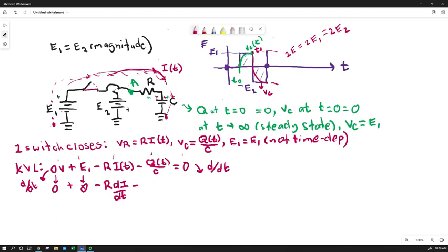So we can say that the rate of change of charge on that capacitor with time is equal to the current flow. If the capacitor were discharging, it would actually be negative. So that becomes important when we start looking at what happens at T1 forward. But for now, when we take the first time derivative of this expression, we're going to get just current divided by capacitance. So that all equals 0.